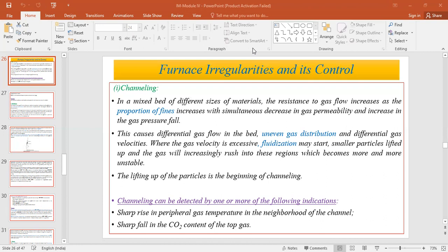air, the preheated air. When it comes in contact with the coke which is present in front of the tuyeres, combustion takes place and reducing gases are generated, especially CO and CO2 in nature. These travel upwards and interact with the solid burden, and that is how the solid-state reduction reaction takes place at the top part of the blast furnace, followed by melting, and the melting process takes place inside the blast furnace.